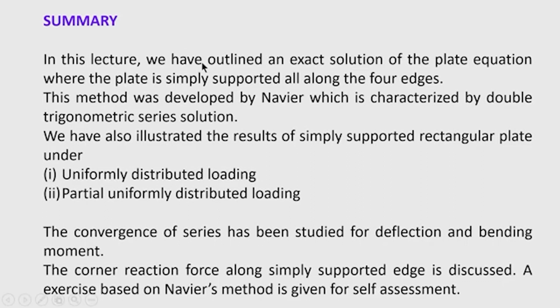Say when you take composite plates or any other thing, this Navier series has to be taken for such a boundary condition, and the simply supported boundary condition is very common, and it provides the benchmark result for various complicated problems. So, therefore, this problem that we have discussed in today's class has significant impact on various other results that we will obtain in future or will be used in research projects.